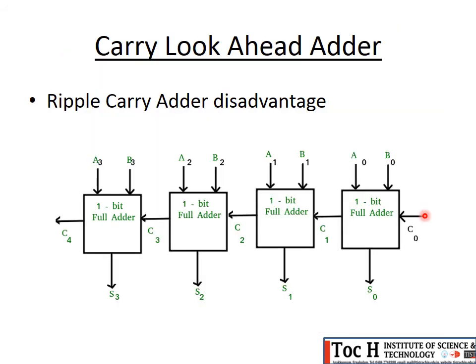Next comes another type of adder, that is the carry look ahead adder. It is also another adder configuration. This is not actually mentioned in our syllabus, but it is also an important adder configuration, so we will just refresh the basic concept. It is a fast parallel adder, as it reduces the propagation delay by using more complex hardware. Hence it is costlier. As we make the hardware more complex, the cost increases.